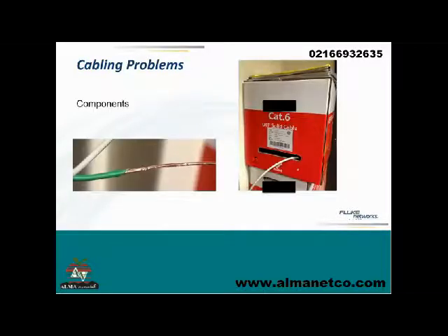Another thing that can be a problem is components. And this is pretty rare, but it can be a real disaster when it happens. One of the biggest problems we've seen out there in the world is what's called copper-clad aluminum cable. In an effort to save money, there are some manufacturers out there making a cable that's not copper, it's aluminum, and then it just has copper around the outside, so it looks like it's copper.